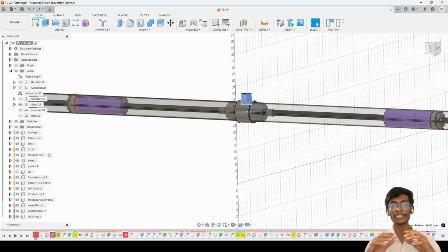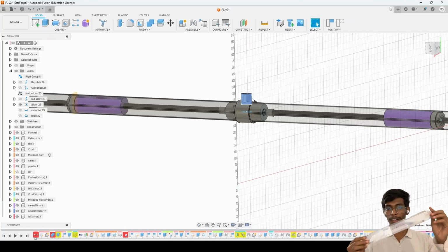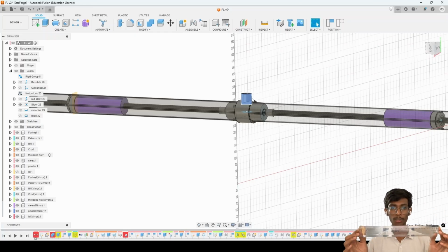And the system would not just tilt like this. A normal system would just tilt like this. If you move the center of mass from here to here, it would just tilt. But because it has two counter rotating motors, they are going to induce some gyroscopic precession and some angular nutation, and Coriolis forces are also going to come into play.